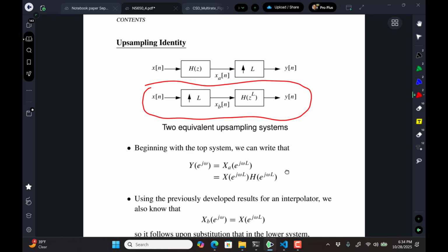But yet, what makes this obviously dumb is that this pumps in a lot of zeros. So this filter is seeing a lot of zeros get stuffed into it, which means there's multiplies that don't really do anything if you multiply them by 0. So that identity up above says that no, we can filter first and then upsample and make it more intelligent.